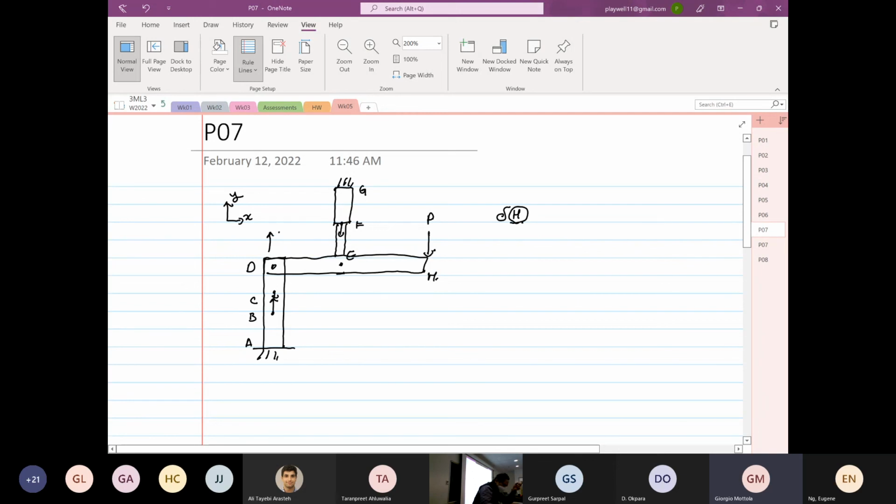Delta D is free to go anywhere; it can go up and come down. Delta E can also go up or down. It's free to move. A lot of you thought it's not free to move. That's why you went into redundant analysis. And this problem is very simple. I'll tell you the procedure. If I tell you the procedure, you'll tell me, Eugene, that's it? And I say, yes.